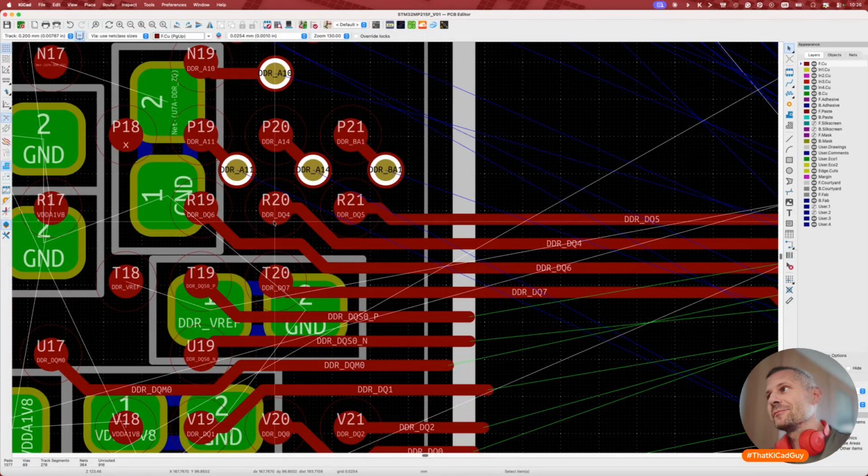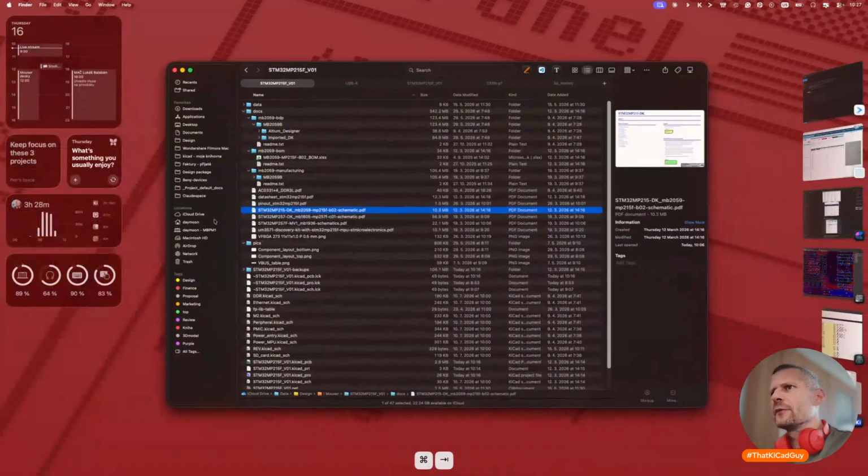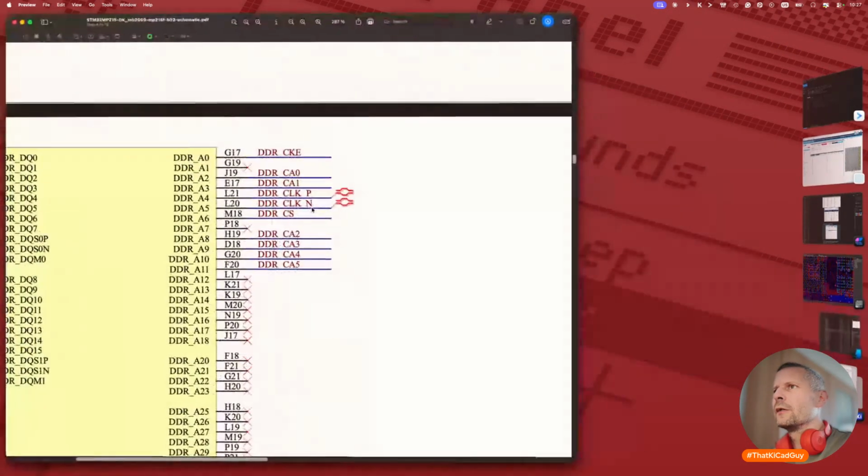I can't connect the DDR DQ data buses. It's a memory. We can connect any bit of the controller to any bit of the memory. The bits stored in the memory don't need to be in the same order as in the MPU, but I don't know if I want to do similar tricks.